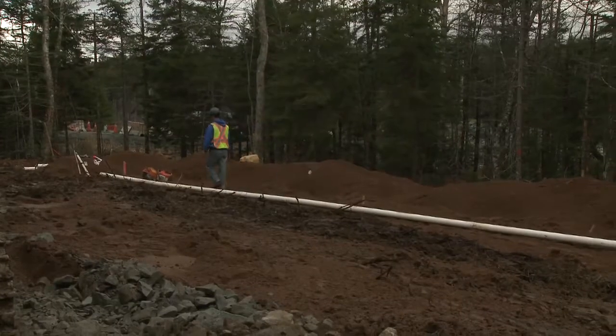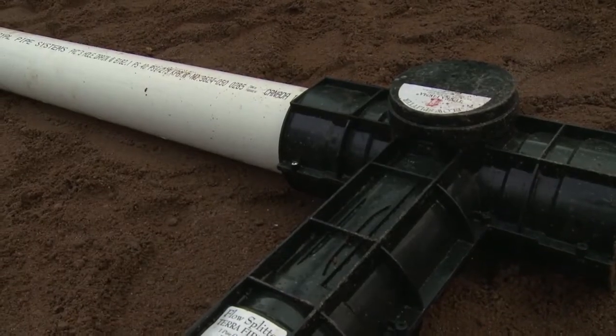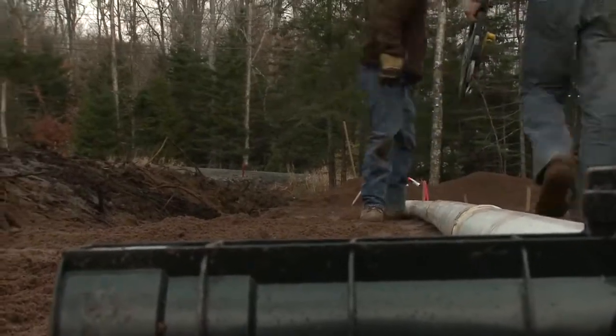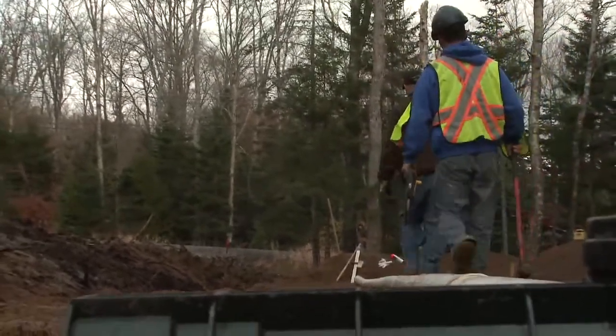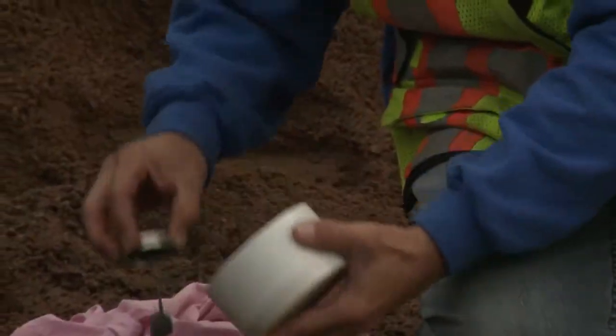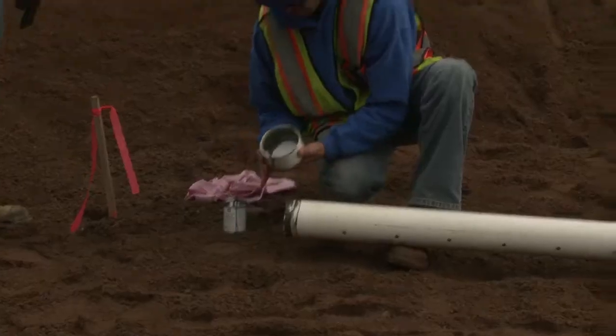If the bed is to be center-fed, the pipe is cut in the center and a T is installed. The pipe is positioned on the filter sand 1/3 the width of the trench, from the back of the trench. An end cap is installed on each end of the pipe.